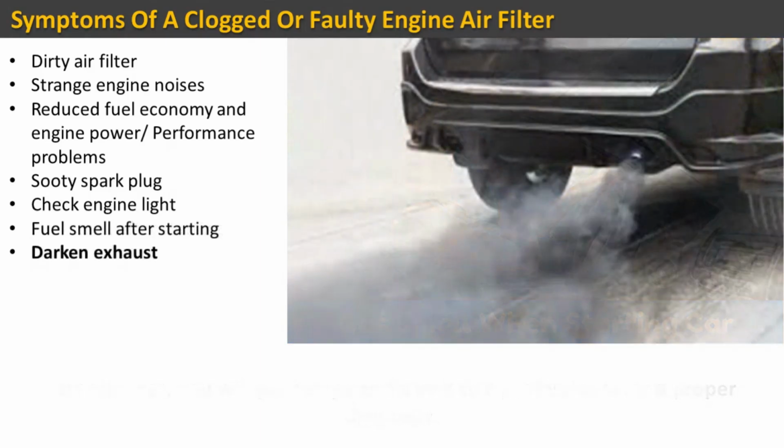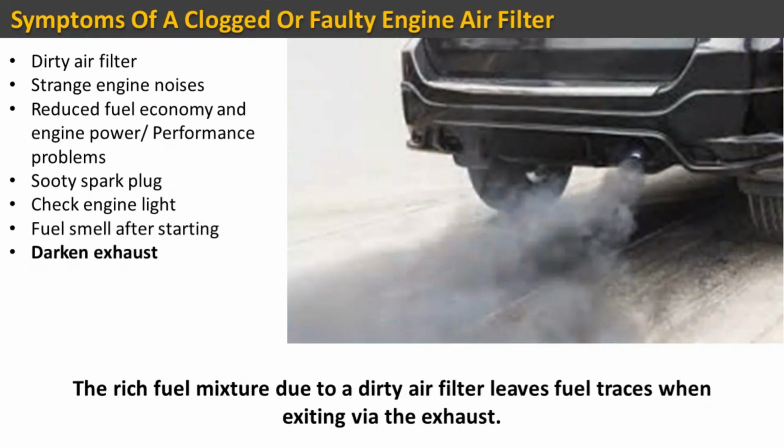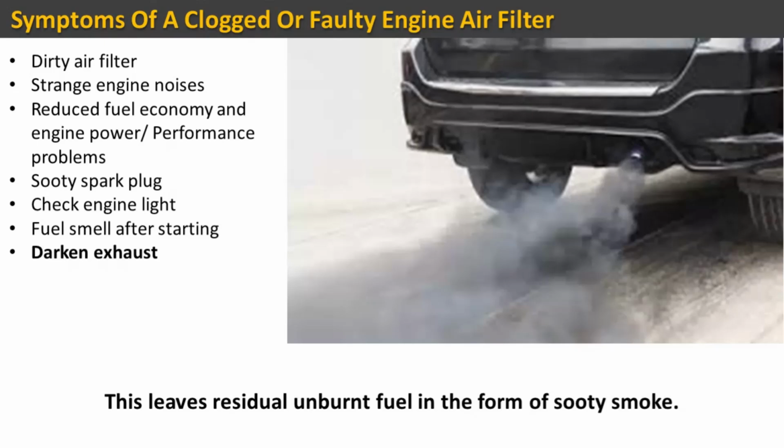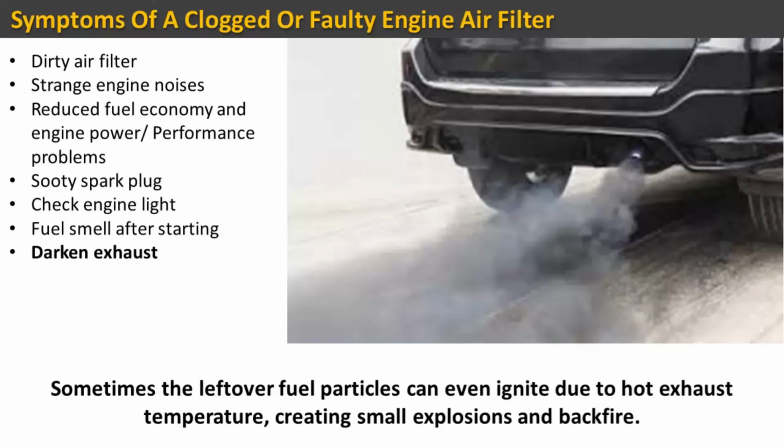Darkened exhaust. The rich fuel mixture due to a dirty air filter leaves fuel traces when exiting via the exhaust. This leaves residual unburnt fuel in the form of sooty smoke. Sometimes the leftover fuel particles can even ignite due to hot exhaust temperature, creating small explosions and backfire.